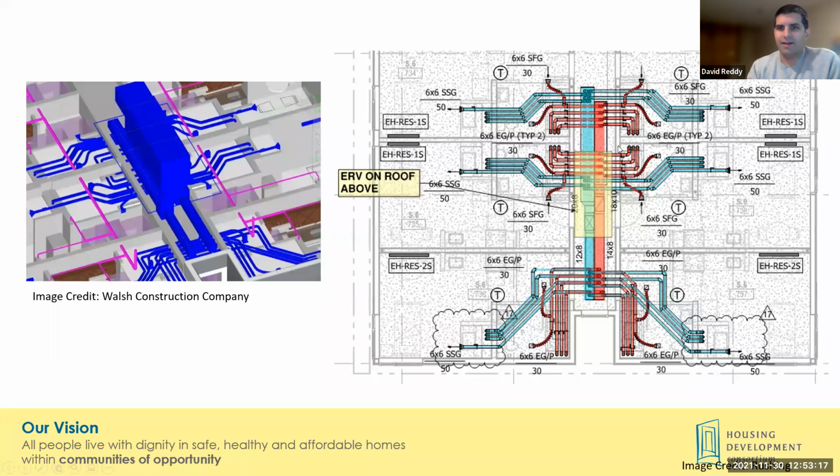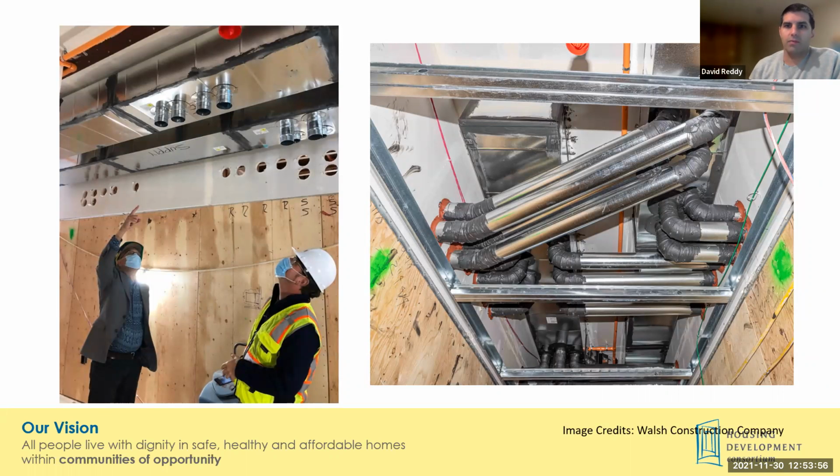You can see, one architect I've worked with dubbed this the octopus design, with all these tentacles emanating out from the ERV, and truly it looks quite muddled and complicated. But once these are all 4-inch ducts, and once they're laid out with the idea of dropping off these main trunk ducts, and provided there's sufficient space, it was, well, I wouldn't say easy, but it laid out nicely in the end. Here's some nice pictures of how that worked out.